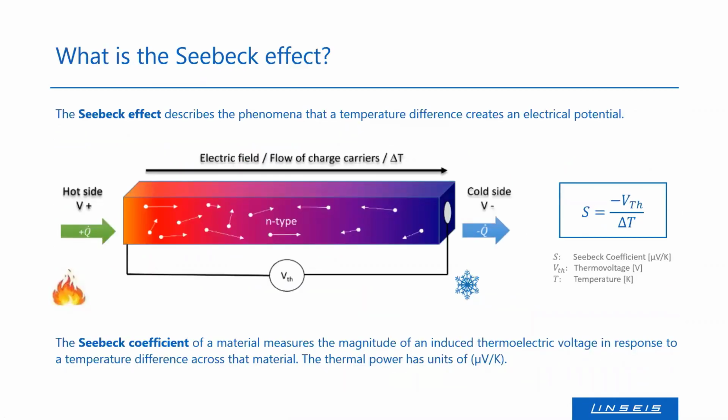Generally, if one talks about thermoelectric phenomena, or in particular thermoelectric generators, it often refers to the usage of the Seebeck effect. The Seebeck effect generally describes how a temperature difference along a conductor creates an electric field and, in consequence, the so-called thermal voltage. The basic effect can be explained using this illustration, where we see a conductor, for example, a typical thermoelectric material like bismuth telluride, which gets heated on one side, here on the left, and stays cool on the other side, here the right side.